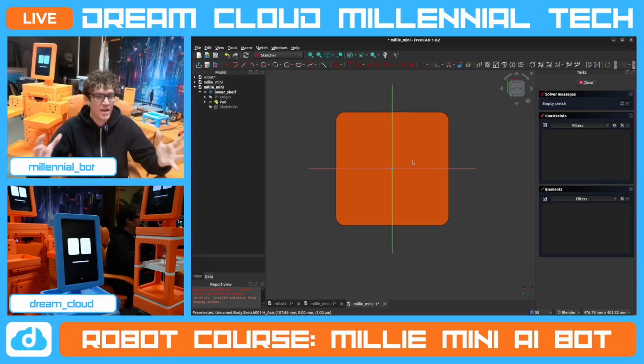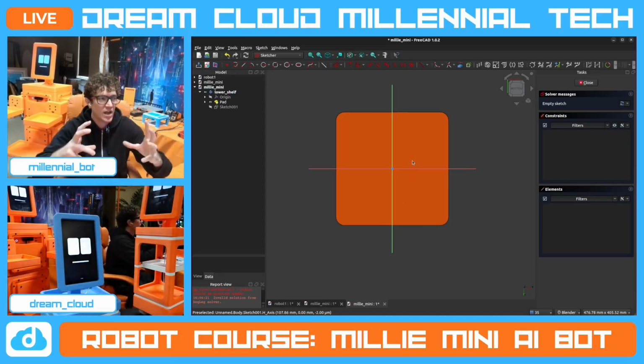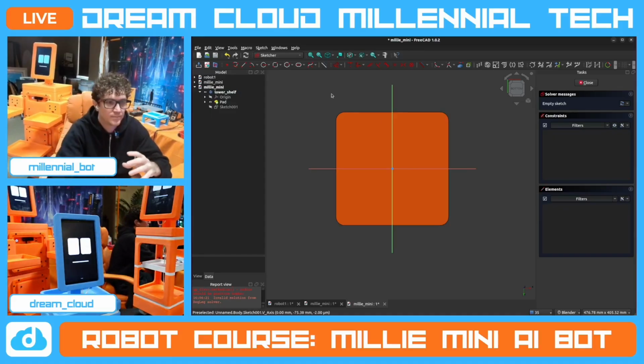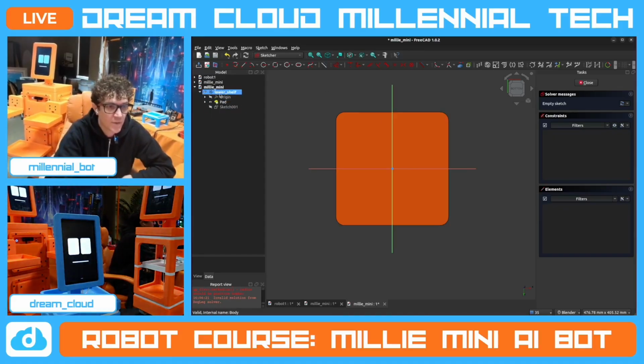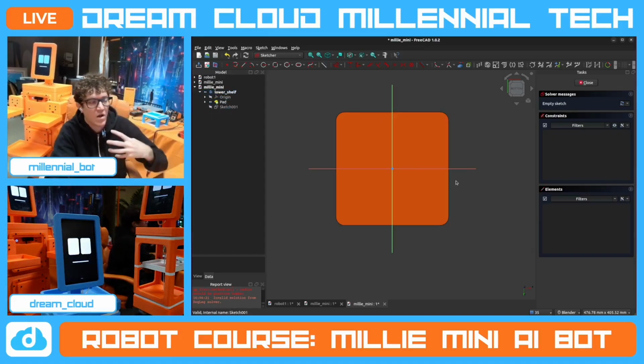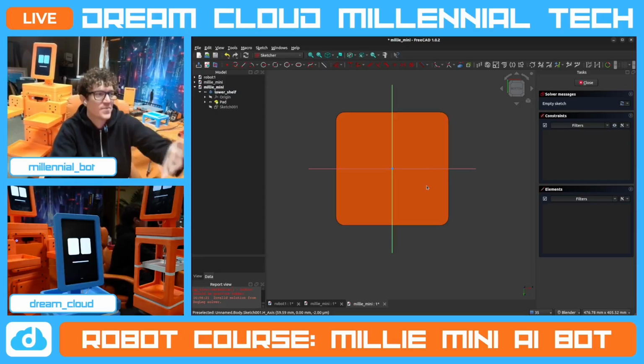So just think about that as you've got these 3D objects, which are these bodies that we created. And then on those bodies, you have surfaces. And then on those surfaces, you can create sketches. And then those sketches, when you pad or pocket, will change the form of that body from drawing on the surface of that body, right?